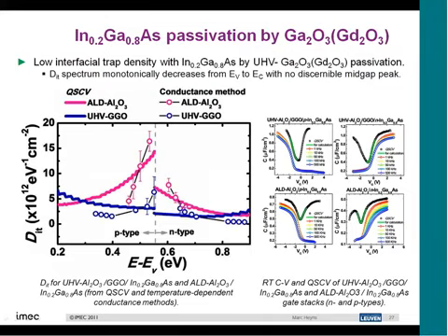The dark blue here, you see that with the gallium gadolinium oxide, you definitely get lower Dit levels, especially here again in the middle of the band gap, than what we get with aluminum oxide ALD, which again points to the importance of this UHV treatment, controlling the surface and making sure that whatever high-k you deposit on top of it doesn't disturb the surface conditioning.